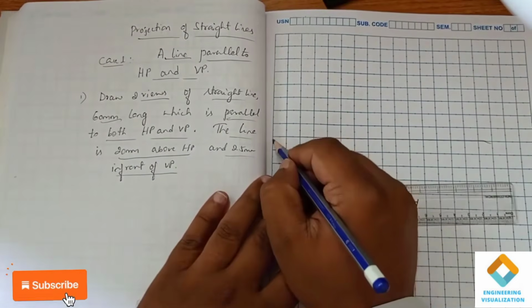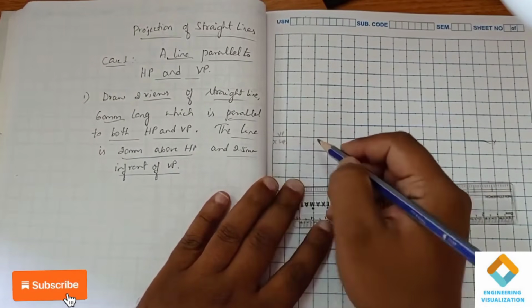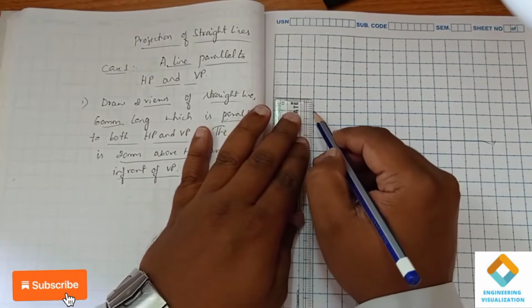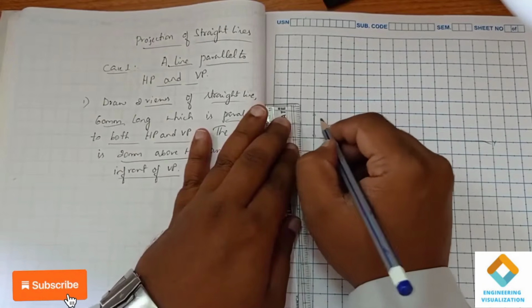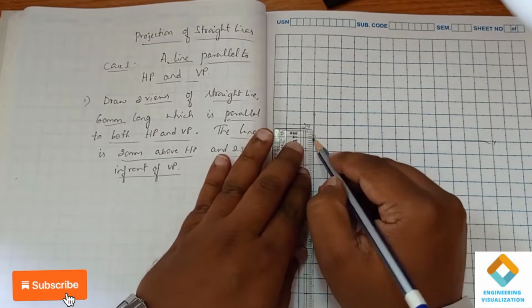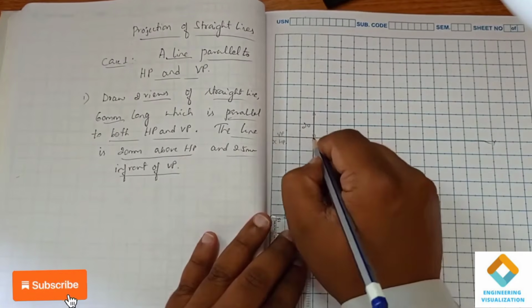Okay, so XY, VP, HP, first quadrant. The line is 20 mm above HP. Above HP means it is our front view, so here vertically I am marking 20. And it is 25 mm in front of VP. In front of VP means it is our top view. So it is 25.